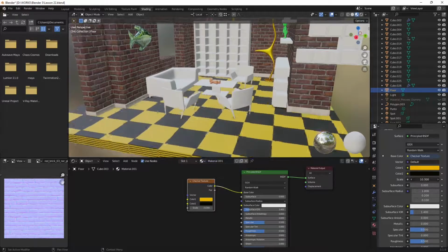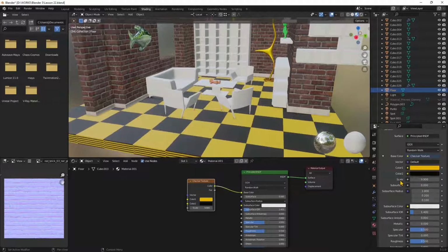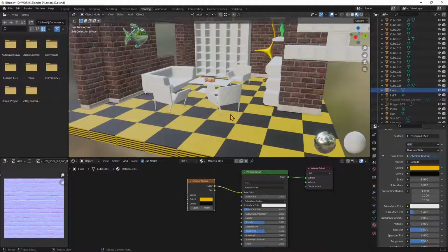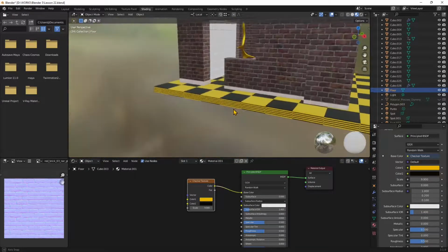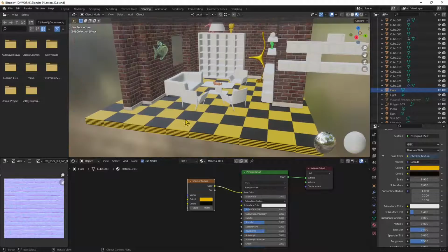This is, let's say, the first way we can map our material onto the object. Sometimes when you use procedural maps, you will have scale, and you can also translate this into another important term, which is tiling. When we use a texture, it should be tileable. If it's not tileable, you cannot repeat it more than one time; it's just a single repetition texture. But in most cases, you will have tileable and repeatable textures, so you repeat them many times and cover large surfaces with just a single texture.